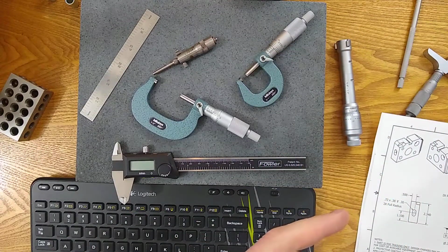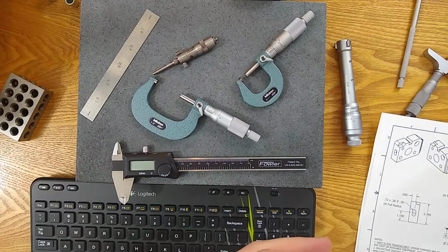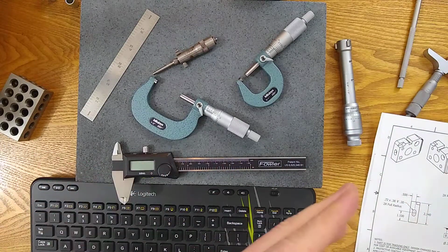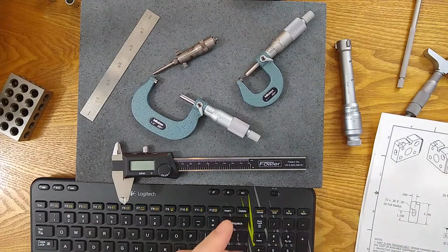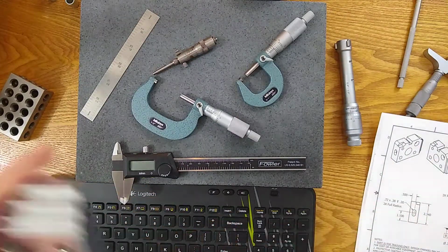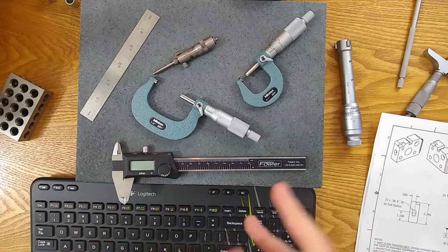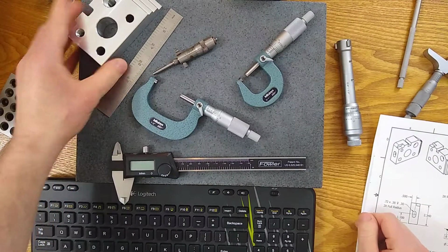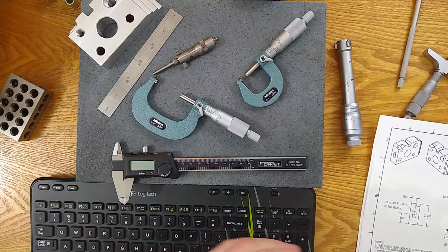Or I might have taken it to a CMM because it's easier to use a CMM than the dial bore gauge, and you still get that same accuracy. I've relied on the CMM many times for cases where I could have used a hand tool or a surface plate tool, but it's easier with a CMM, and I still get that accuracy, and that's okay. And then as I got better with all the tools, I started to use the surface plate tools more and more, and the hand tools more and more, until I got to a point where I was comfortable with all of them. But it takes a while to develop that. With the wide variety of tools in the industry, it can take time.